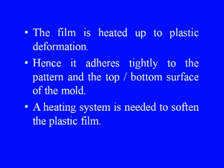Plastic film holding and the heating system. In order to prepare a mold, 2 plastic, polythene, ethylene vinyl alcohol films are used. The purpose of using 2 plastic films, one on top and the other at the bottom of the molding box, is to seal the box. The film is heated up to plastic deformation. Hence, it adheres tightly to the pattern and the top or the bottom surface of the mold. The heating system is needed to soften the plastic film.